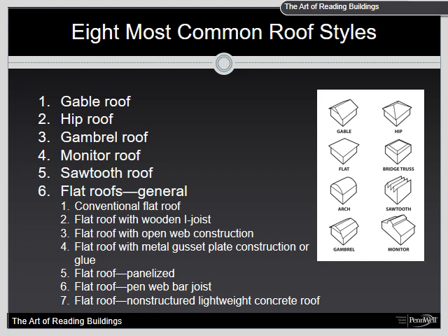When determining the extent of fire in a gambrel attic, it is easy to visualize what a heavy load of stored material would do to supporting lightweight structural members. Roof ventilating operations would be extremely difficult due to the design of a gambrel roof, unless attempted by an aerial device.